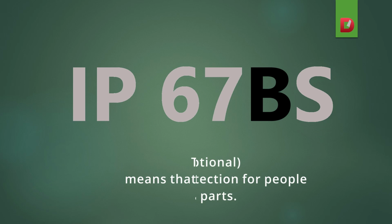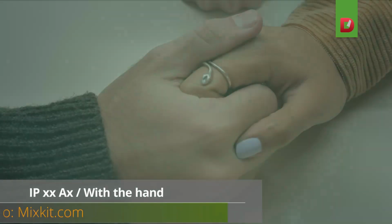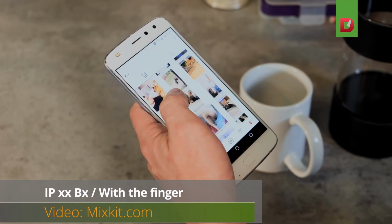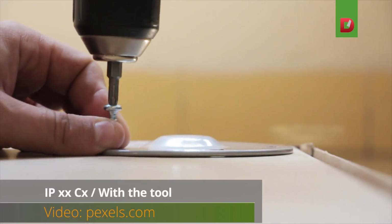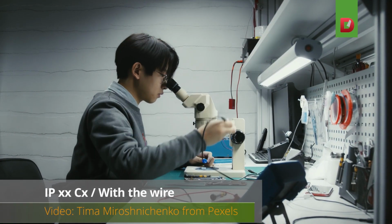The first additional letter means that the enclosure provides protection for people against access to hazardous parts. Letter A means protection against access to hazardous parts with the hand. Letter B means protection against access to hazardous parts with the finger. Letter C means protection against access to hazardous parts with the tool. Letter D means protection against access to hazardous parts by wire.